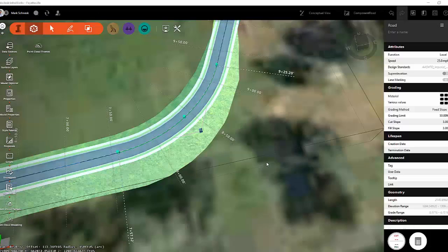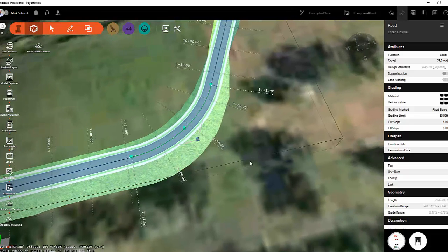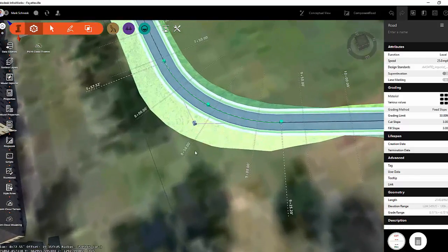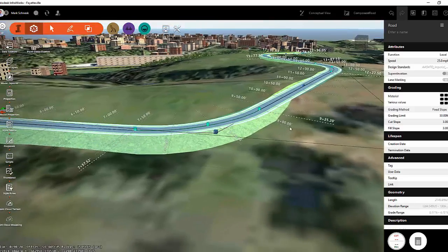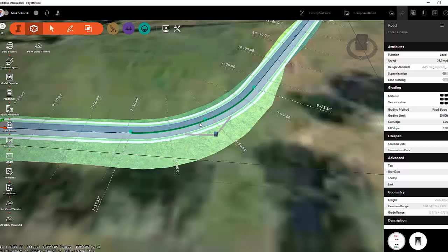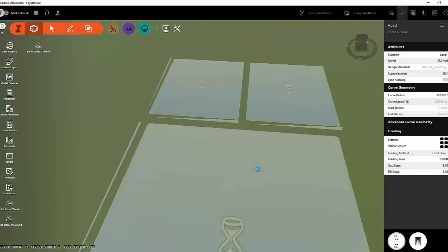Also included in the new version of Infraworks are fixed increment station labels that display for the selected component road. They move and vary depending on zoom level in both the horizontal and the angle view for vertical and profile geometry. In-context messages provide instant feedback for the roadway curve and spiral layout, providing you length and radius, as well as a contextual area where you can change these components, providing instant feedback and easy design changes.